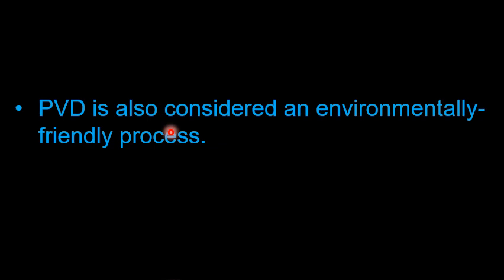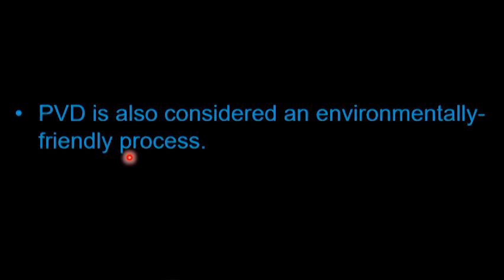Whereas in the chemical vapor deposition process, you basically evaporate a precursor material which is an organometallic, and it is usually hazardous, and when you transport it on the surface of the substrate, they undergo a chemical reaction, and due to the chemical reaction and deposition of the thin film, you get a byproduct which is usually hazardous. And that's the reason PVD is considered a more environmentally friendly technique as compared to the chemical vapor deposition process.